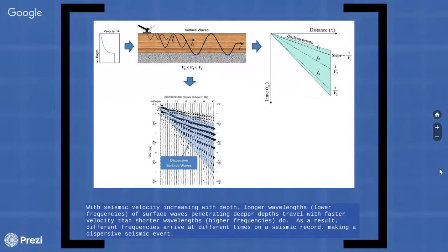Because of this, surface waves are often used to deduce secondary wave velocity properties of near-surface Earth materials, in comparison to using conventional body wave methods to achieve similar secondary wave velocity information. For example, secondary wave refraction, reflection, and downhole cross-hole surveys.